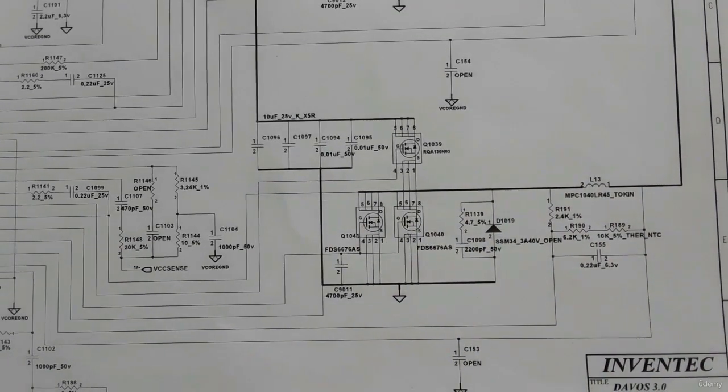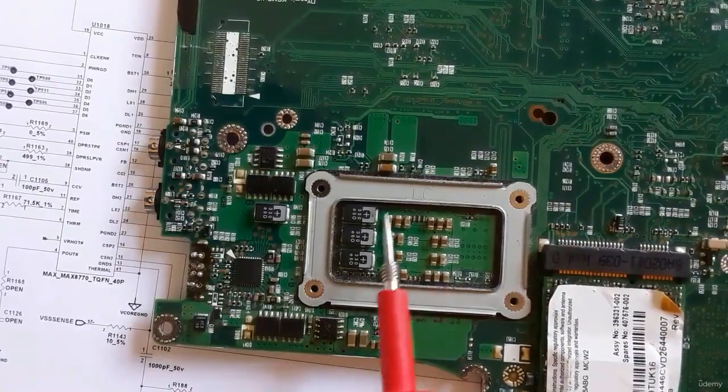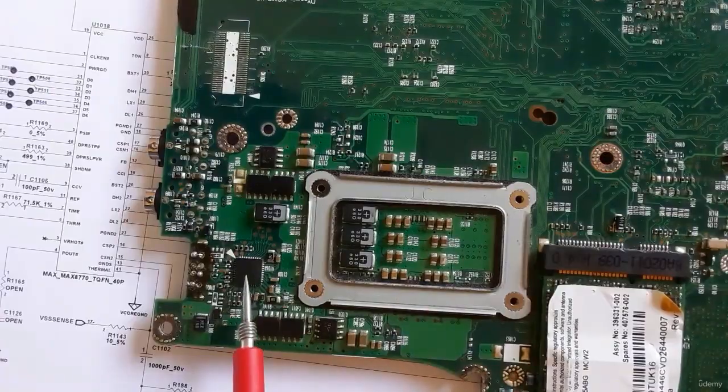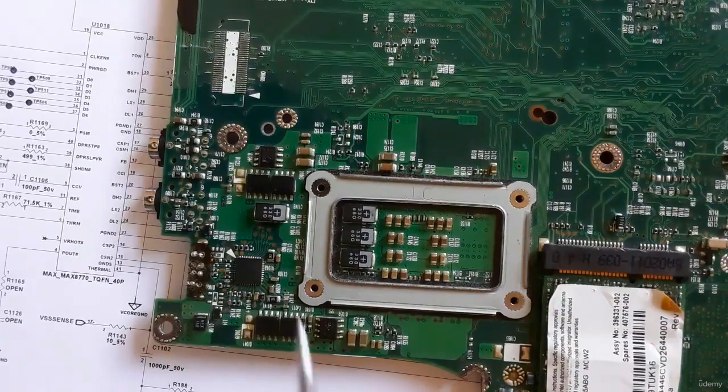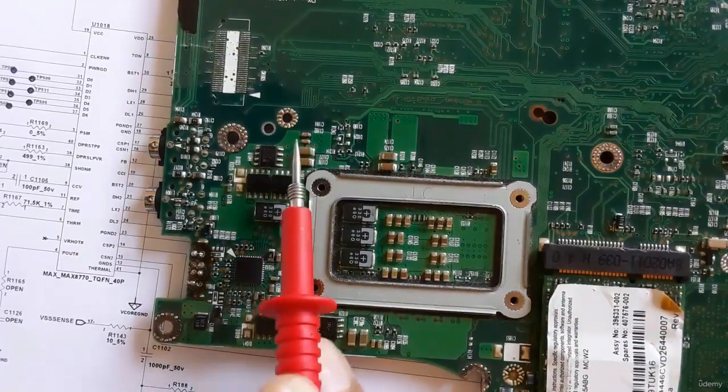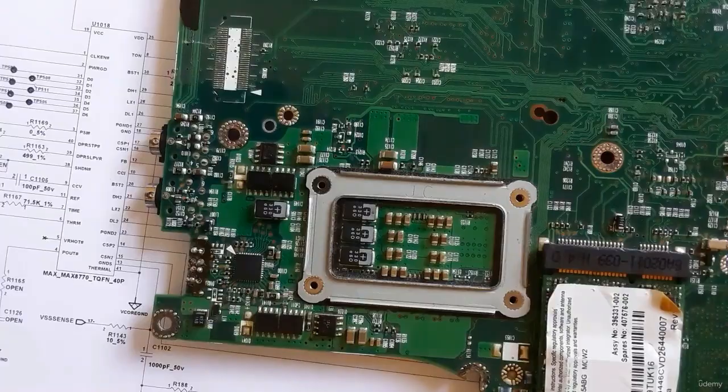Okay? Here in the motherboard, as you can see, we have many ceramic capacitors. So we have the IC, which should be checked. We have here the ceramic capacitors around the IC. We have the MOSFET, which should be checked. Okay? The ceramic capacitors, as you can see, should be checked against the ground. Also here in the other channel, you should check the same components.